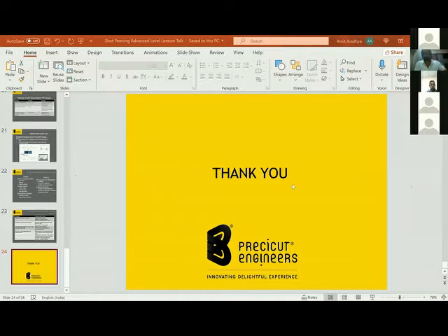Some customers demand 200% coverage. Will it increase compressive stress beyond saturation? Yes, it increases the compressive stress. Will it help in increasing the fatigue life of components? Yes, if the compressive stress is going to increase, so is the fatigue life, but within that given range, which is decided by the customer. So the question again is this: some customers demand 200% coverage.